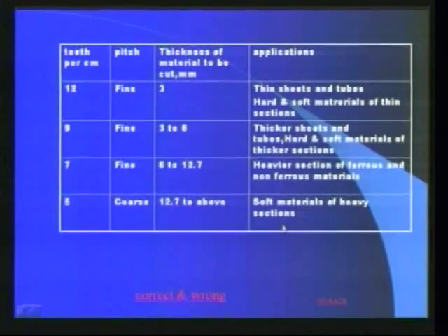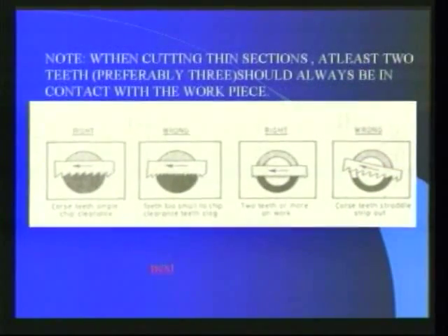We discussed already that when cutting thin sections, at least 2 teeth, preferably 3, should always be in contact with the workpiece. We take some of the applications about the right way of using blades.